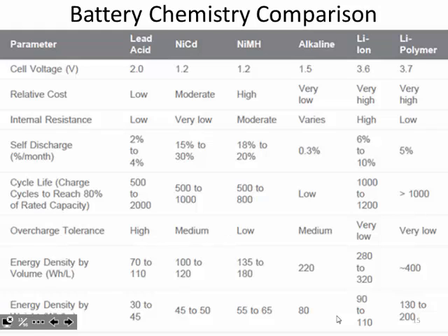If you look at this, self-discharge is how much it discharges with nothing connected to it. It will sort of bleed off its energy into its surroundings slowly. Lead acid batteries have a very low leakage. So do alkaline batteries. That's why the alkaline batteries is like 0.3% per month. So that's why these have a very long shelf life. That's why they can actually calculate an expiration date, when you've lost so much that they're sort of worthless. So long shelf life, very cheap. That's why these are great.